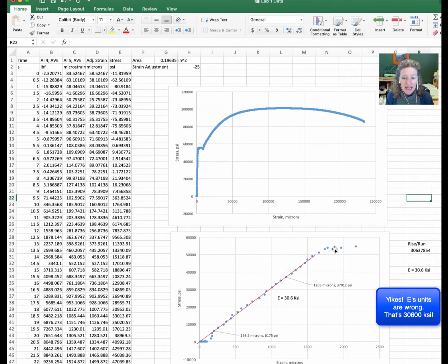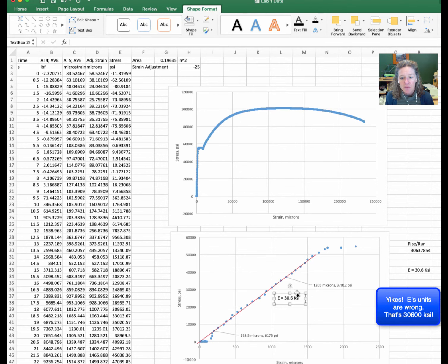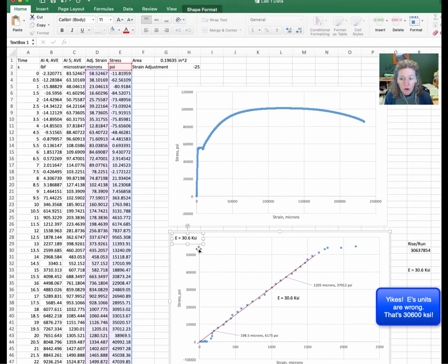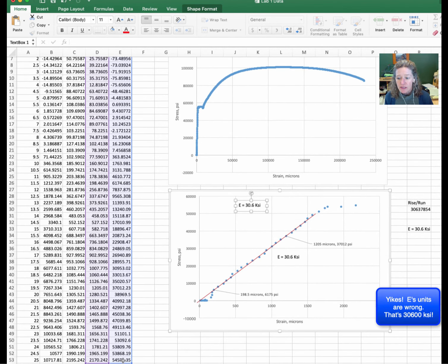And we can identify basically right where we're yielding because it's elastic perfectly plastic. So we could also mark our yield stress or even just have a text box. And we only report these values to 1 decimal point, or we just do them as straight whole numbers. And so we know we're yielding basically at 55,000. So we could then say that our